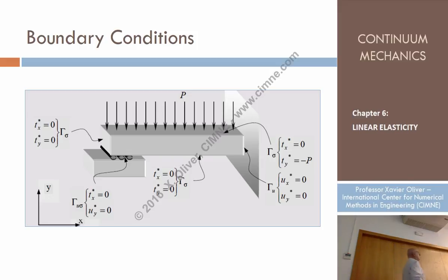You are familiar with that. So let's consider this beam. This is a clamped and supported beam. The beam is clamped at this end, so all displacements are prescribed, and it's supported at this plane. Let's consider the 2D case, so you just look in that dimension and that direction. So what happens with this surface here? Here we know that the displacement x is 0 and the displacement y is 0. That is what we say when we have a clamp, un empotramiento.